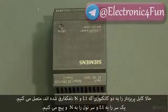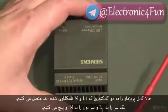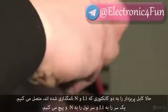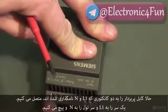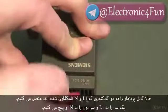Now we need to connect the cable with the power plug to 2 sockets marked as L1 and N. We insert the phase conductor into L1 socket and the neutral conductor into the N socket and screw them in.